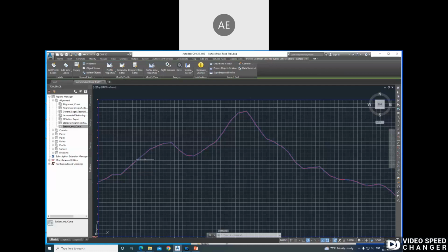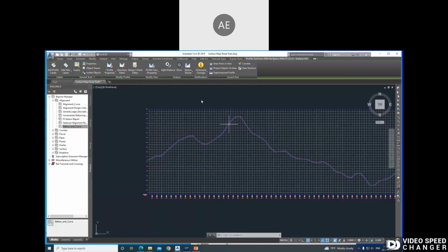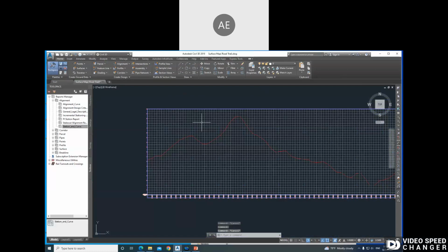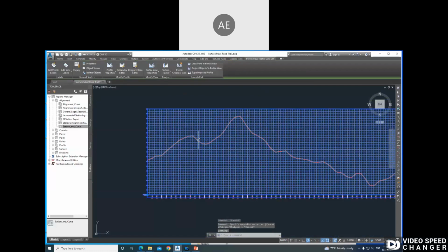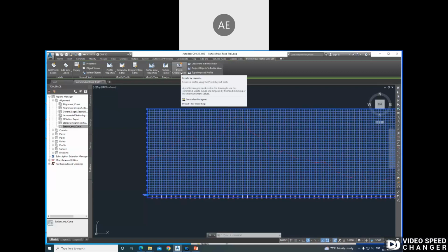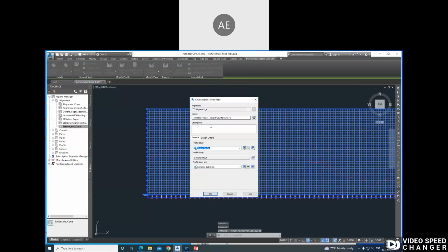We have something called here. We press okay. We press on this one here. Yes, press on. It's called the profile creation tool. So now we will create a new elevation, a new road. We call it the proposed design elevation, where we have the trajectory done according to the restrictions that we will assume. So press it. This is of course for alignment X. If you have several alignments later on, you can select the one that you are working with.